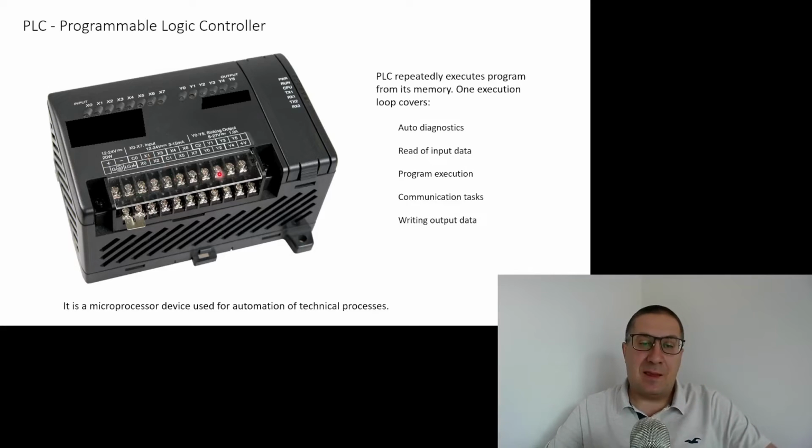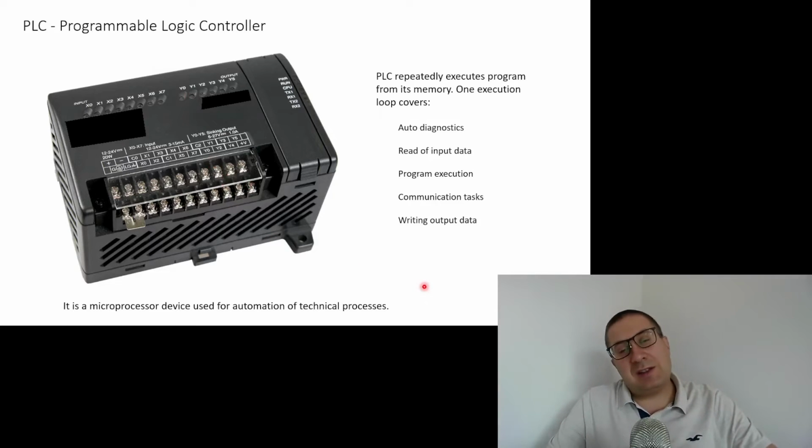So the cable to the pump is connected to the, I don't know, Y0 pin, and the algorithm will send the decision to the Y0 pin to stop the pump. A very simple algorithm. And it will be executed in a loop every second, 10 times a second, or at other frequencies.